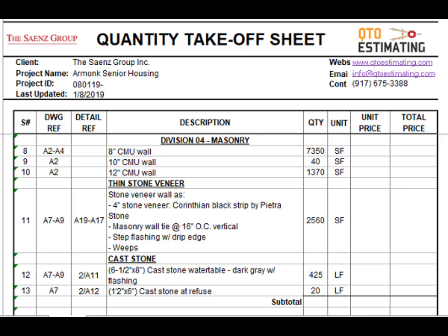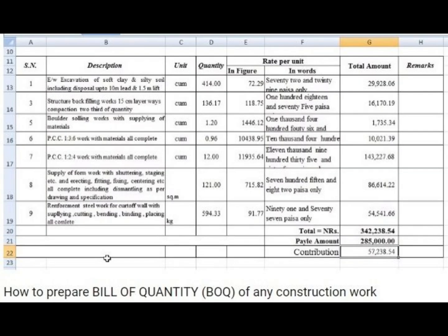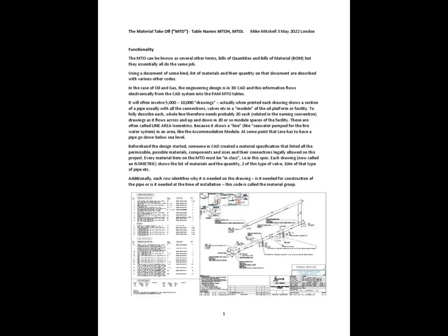Step 3. Define a clear MTO structure. A perfect material takeoff is structured before it is quantified. Divide the takeoff into logical sections such as equipment, piping, valves, supports, instruments, and miscellaneous items. Each line item should represent one measurable and purchasable component. Clear structure makes the takeoff easier to review, price, and audit.